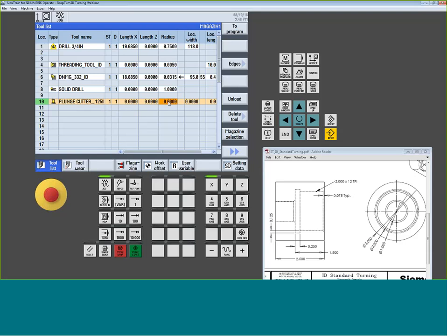Okay. We are going to ask for the corner radius of the tool because I can come in and do a little profiling or finish pass with this tool. So let's say, for argument's sake, I happen to know I had a 5 thou corner break. What is the physical insert width? This is important. So this is that 125 or that 1/8 inch wide we just mentioned.